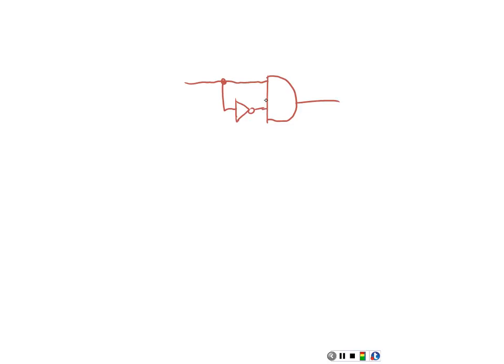So when we look at Boolean algebra, let's make this a NAND gate, because that's what I've got. I got a 7400 up here, which is a quad 2-input NAND gate. What Boolean algebra would tell us is that if we call this x, x would equal, here's my input right here, so this would be A, and then this right here would be not A. Right? You understand? So what that means is it appears that I could never have all highs.